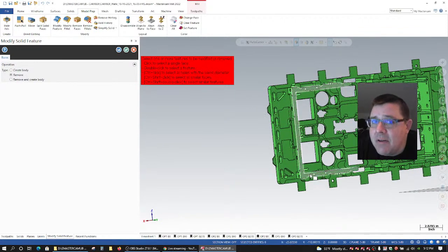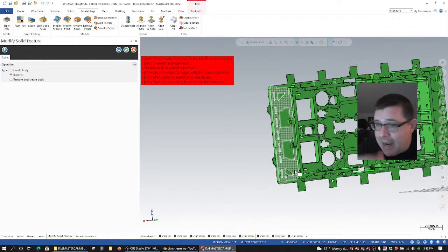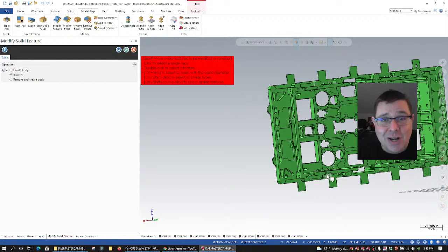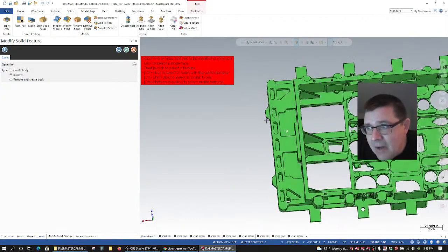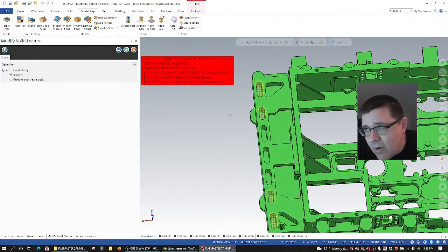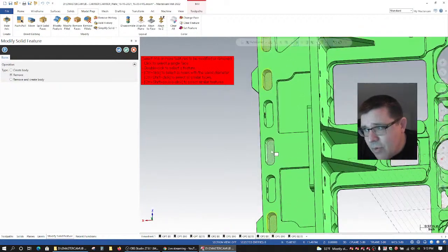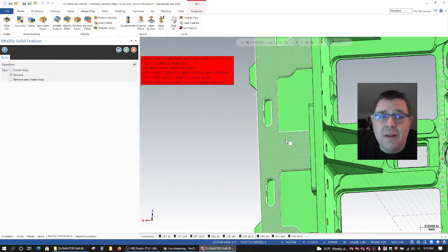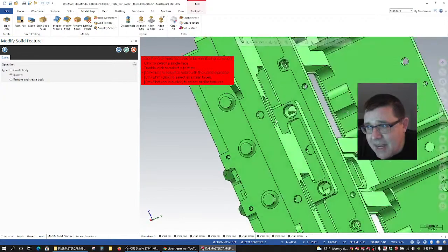Again, I've made a copy of this. This is the manufacturing model for Op 1. In other words, I'm not going to use it. I want to make sure that I'm not doing this on the only copy of the solid I have, right? I need to keep the original solid somewhere so that I can compare it back to it. But within maybe a half hour or an hour of going through and selecting these features and getting rid of them, I can make a significant improvement on the speed that it takes to toolpath these models.